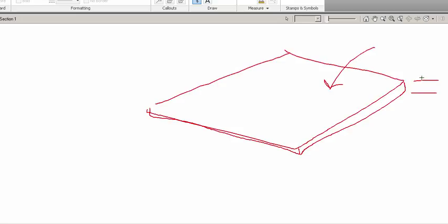And the key thing about them is how thick they are, because that's going to establish a lot of weight. Now the type of surface, you can have diamond plate, you can have your standard plates, all kinds of things, and they will also have a grade of steel or KSI value associated with them. It just depends on what ASTM standard the manufacturing company may have made. But anyway, we use plates in construction a lot.